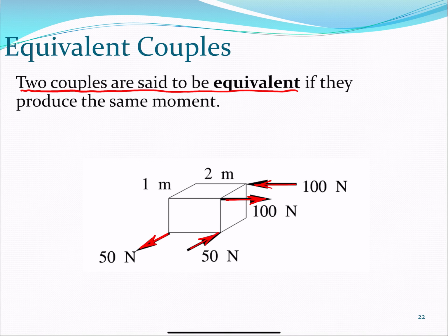For instance, what is the distance between these two guys over here? Well, if we choose a position vector oriented that way, we have to use this force to calculate the moment about that point. We find that the moment creates a rotational tendency going this way, and I have determined the sense of the rotation just by inspection.